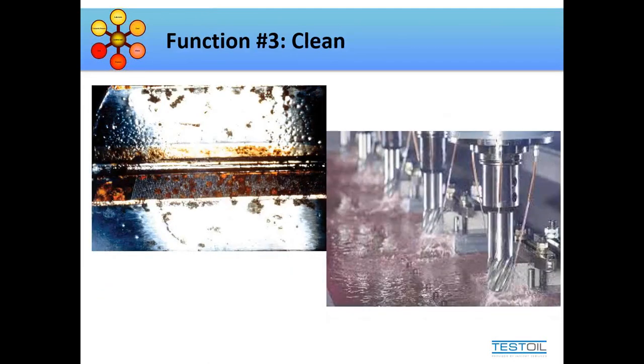Another function is to clean. Just as heat is carried away from your machines, dirt and particles are also carried away. In particular, if you have like a machining process, you get the metal chips in there while you're actually drilling or milling. And if you keep those in the oil, they can go back in, and as you're grinding or as you're milling, they can start to put other scratches in the surface or start to dig in and gouge. So to cut that down, the lubricant actually flushes and carries away those particles so you don't get that back in your process.